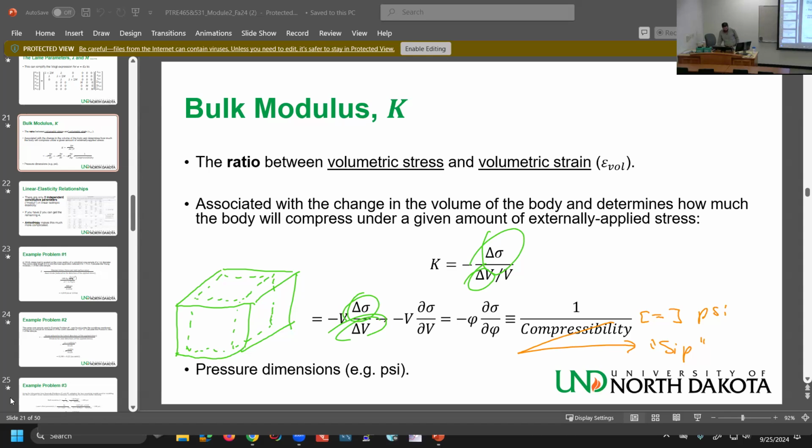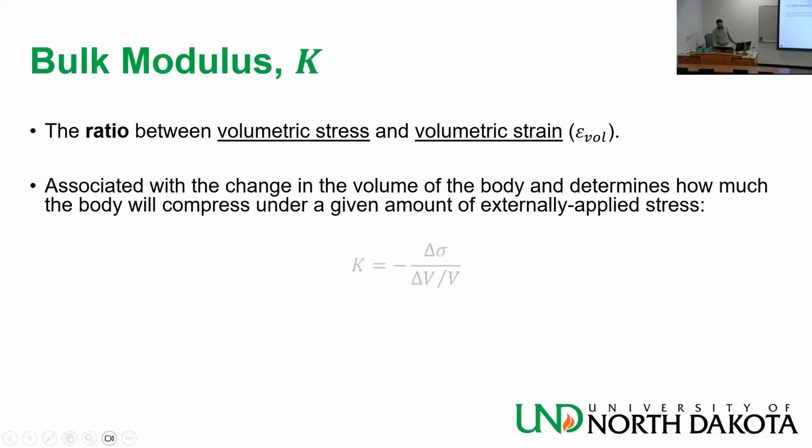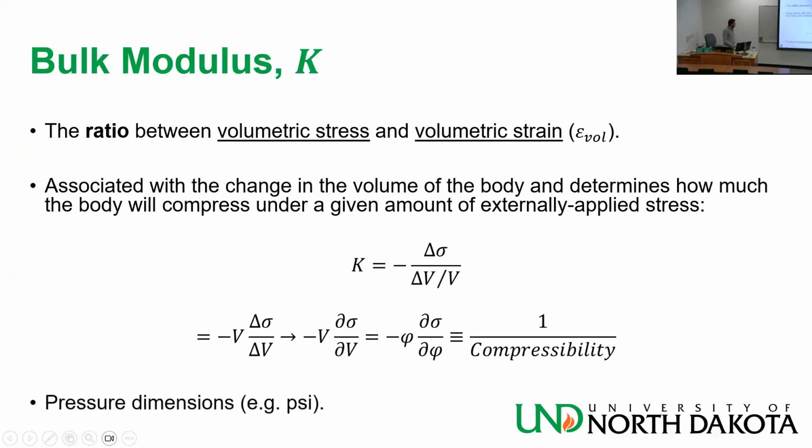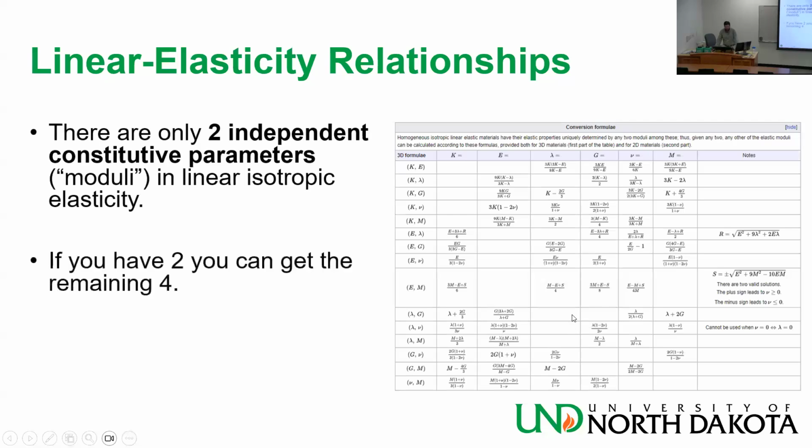That about the Young modulus. And then I did go over, okay, we talked about 6 different moduli. Young modulus, Poisson's ratio, shear modulus, bulk modulus, Lamè's first and Lamè's second parameter. Okay, how are those interconnected with each other? Because like I said earlier, 6 unknowns, 6 equations, but I only need to know 2 of those moduli, and I can get the other 4. And here I have a set of all the equations. This is from Wikipedia, actually.